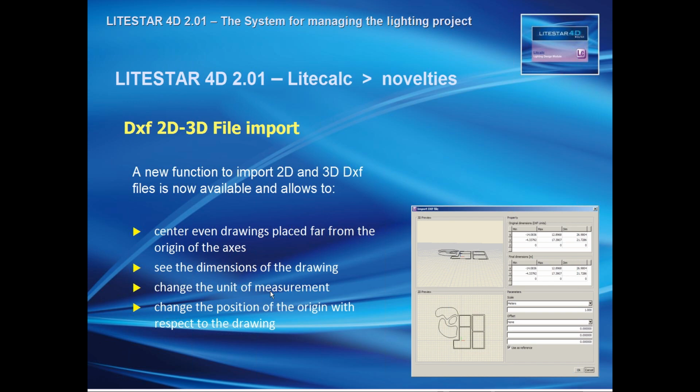Another big change was introduced in the management of the 2D and 3D DXF file import feature. Now whenever you drag and drop or you open a DXF file, it could be a 2D or a 3D, it doesn't make any big difference, this window you have here at your right will appear. This window is capable of managing the center, so it shows the distance in many cases between the origin of the axis and the drawing. In many cases, the drawing is far away from the origin, so usually it is difficult to visualize what the drawing is.